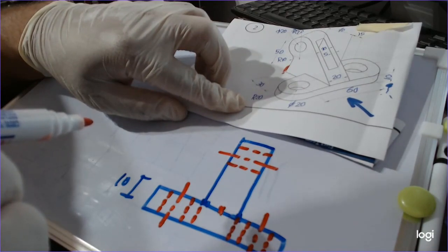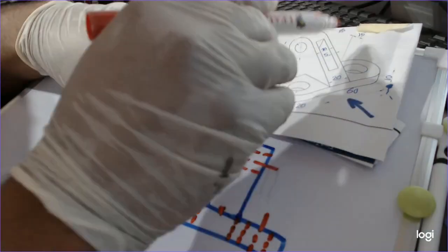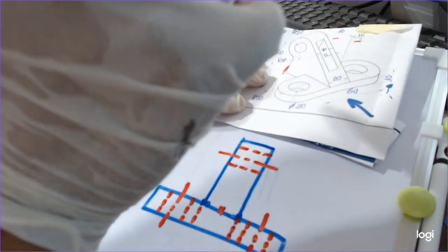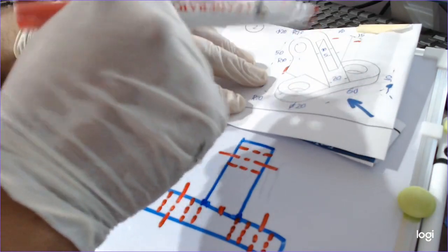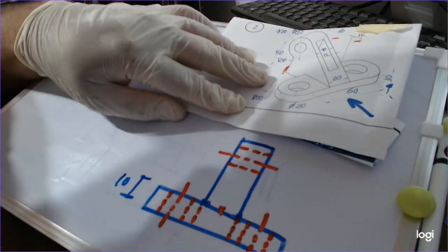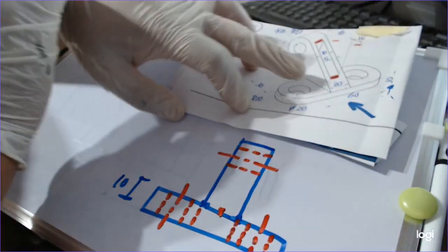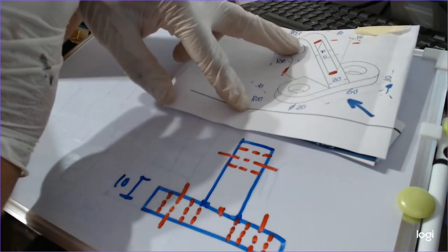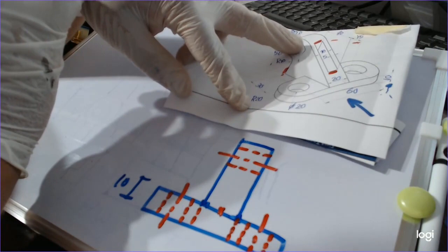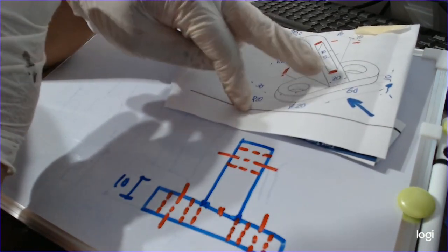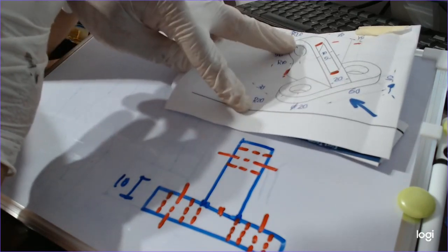Let's say that we have a distance here with 15 and 40, and the thickness will be all around 5 millimeters, but actually we couldn't indicate these slight edges, those inclined edges here. So that means that we have to draw the side view first to indicate the start point and the end point of this pocket shape.